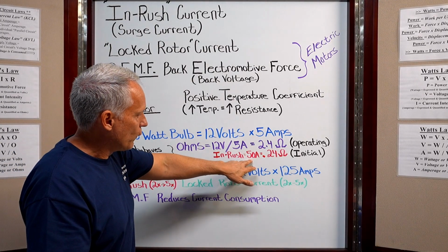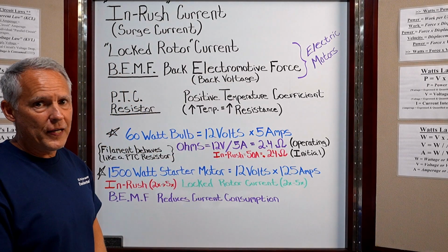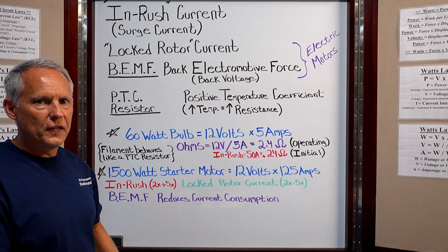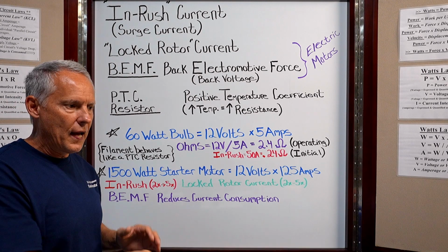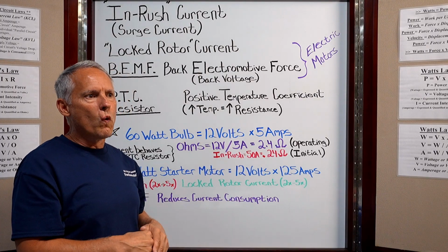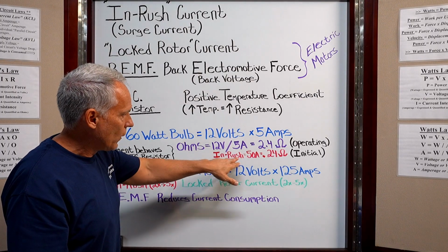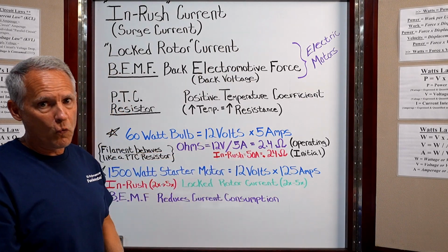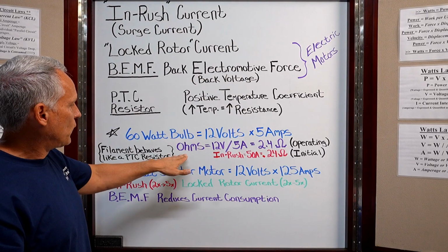Now, to say that you're going to design the circuit to only carry 5 amps, well, you wouldn't want to do that. You need to design it and have a buffer, a margin of protection built into the circuit to where it's more than capable of carrying the load. It sure doesn't need to carry 50 amps, but it's got to be able to carry more than 5 amps, okay? So what I'm saying to you is this.